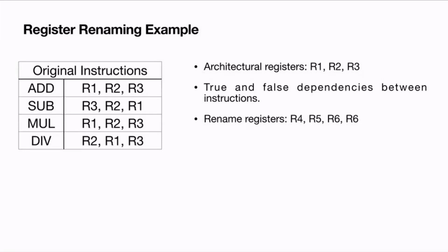So the rename registers are actual registers. In the processor we have registers defined by the actual ISA, those are architectural registers. In addition to that, we have some extra hardware registers available inside, and those are called the rename registers. We will be using those for all these operations. So you can have, for example, around 100 plus total registers, some are architectural registers, some are rename registers. These are real registers only, but from the architecture point of view, ISA point of view, they have no meaning.